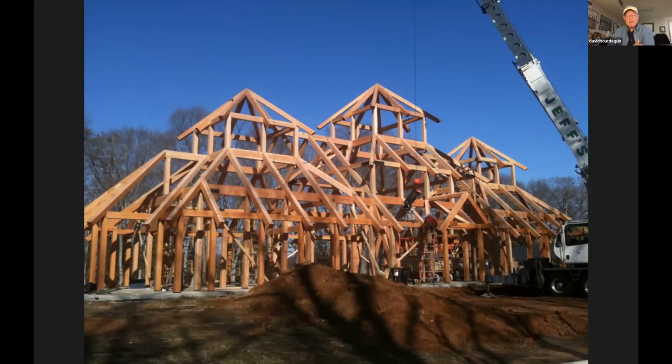Now, as I said, you've got to look at wall openings, of course. If there are wall openings in it, you may have to use tie downs at the jambs of the openings in addition to the timber frame. But usually you try to find enough shear walls that go from one post to the next in each plane to take the lateral loading. Seldom do you ever run into a situation where you can't do that.